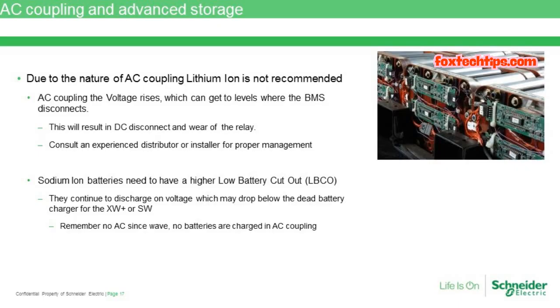So definitely consider that if the size of the system says, gosh, no longer do we need to think about it as 50% depth of discharge, but 100% depth of discharge. As long as we're over that kind of 440 amp hours for the XW Plus or 200 amp hours for the Conext SW, then that suddenly starts to make more financial sense to the customer and could get you to convince them to start with a battery-based system with just the overall cost and getting the most of the return on investment out of that system.